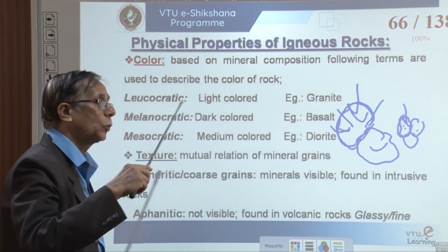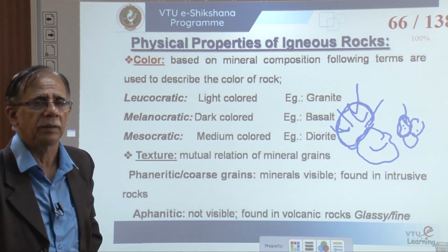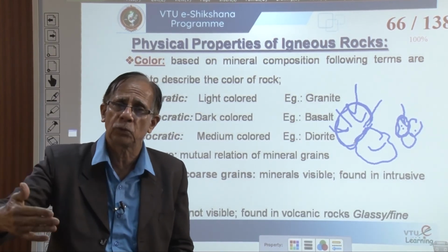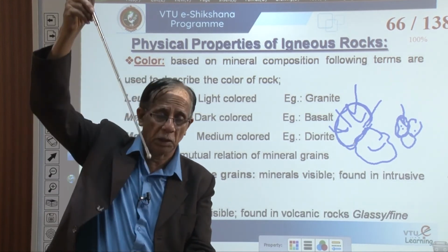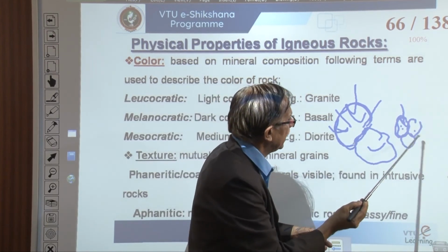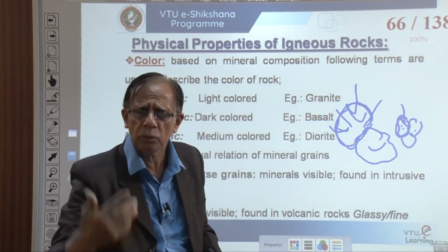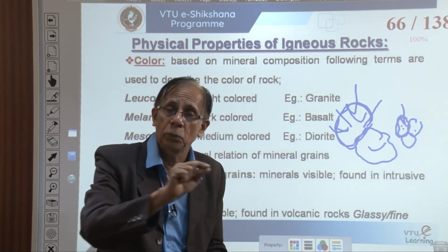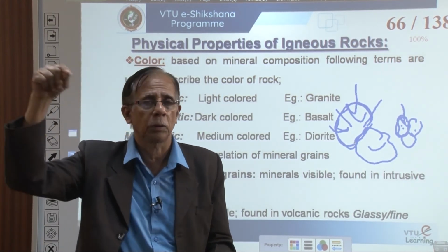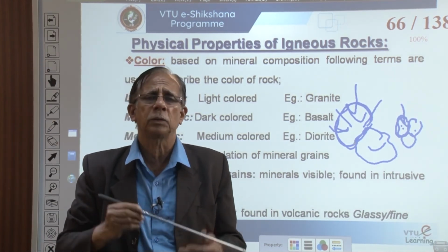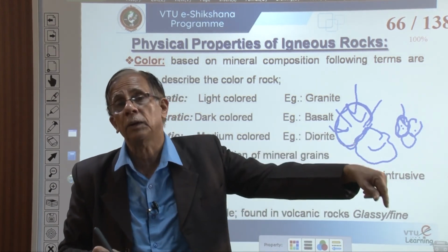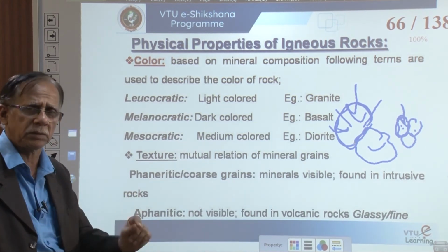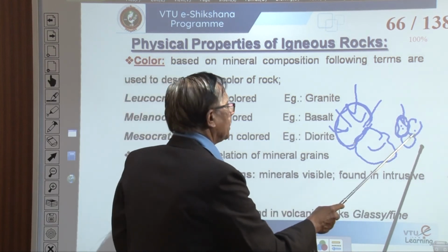Now, when the particles are coarser, we call it coarse grained, otherwise fine grained. Their properties are different. Their response to weathering, chemical processes, etc. is different. Atmospheric agents can attack over a larger area in one case, and only a smaller part of the area in the other, because a small grain has a small part exposed, and a large grain has a large part exposed. Especially when the composition has different minerals. Suppose there is one mineral called quartz, one mineral called feldspar. Feldspar mineral is more sensitive. If that is larger, it gets affected easily. Therefore, the size of the material, the size of the mineral, constituent, grain, crystal, whatever you call it, also matters and also decides.